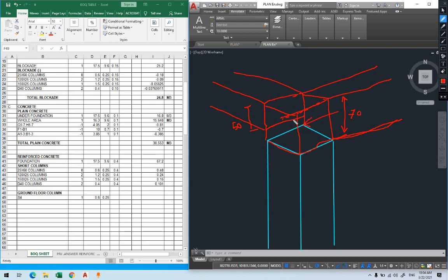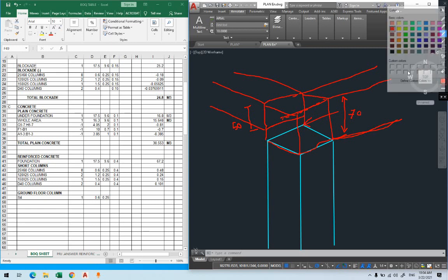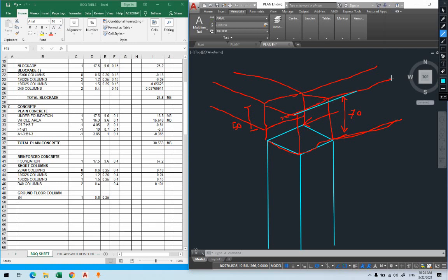It will be filled because when we're calculating the beam, I will tell you that we consider this to be the length of the beam. From here, we'll consider it like this. The beam will be considered like this, the length. But for the height of the column, remember when you have multiple beams on the column, you'll check which one has the deepest height. Then you're going to use that one in order to calculate the height of the column.